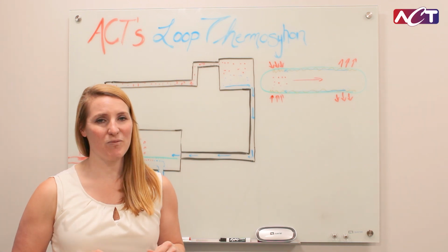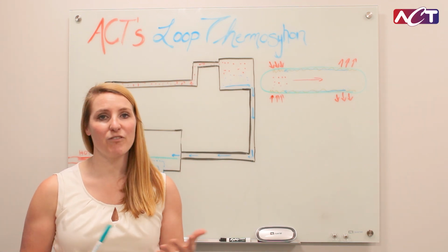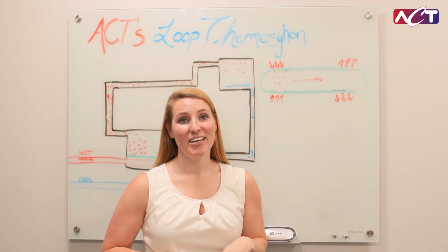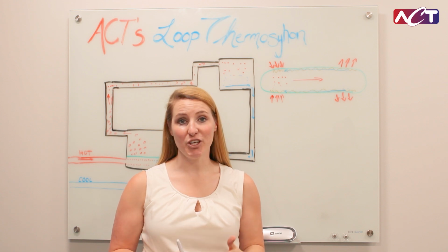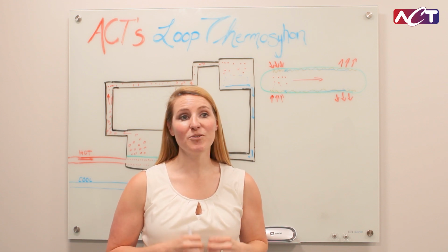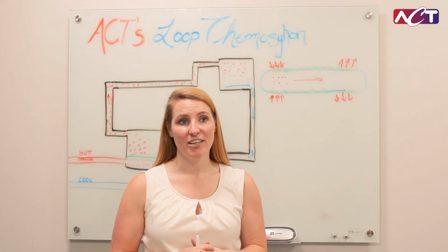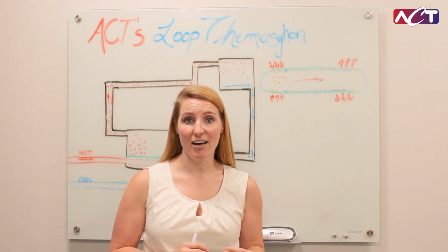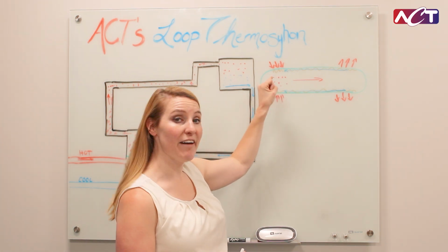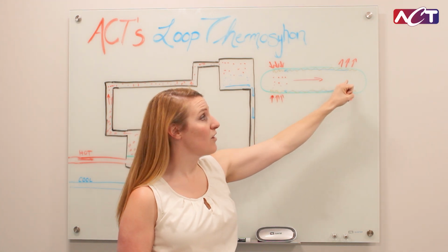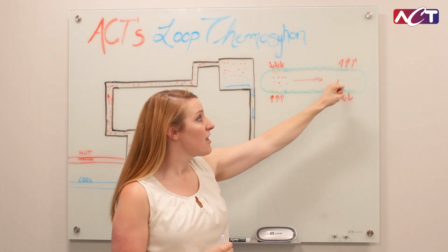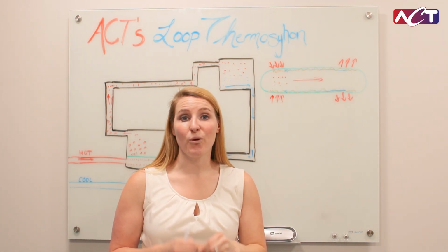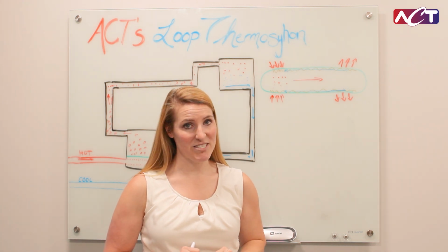The way a Loop Thermosyphon works is very similar to a heat pipe, for those of you who have experience with heat pipes. A heat pipe operates in a closed system. This means that it operates along the saturation curve of the working fluid. It also leverages the latent heat of vaporization. And both liquid and vapor are present in the heat pipe at all times. At the hot spot, the liquid vaporizes. That vaporized fluid moves to the area of lower pressure or cooler area. The vapor then condenses and returns back to the hot spot either via gravity or the wick. If it's gravity, it's a thermosyphon.